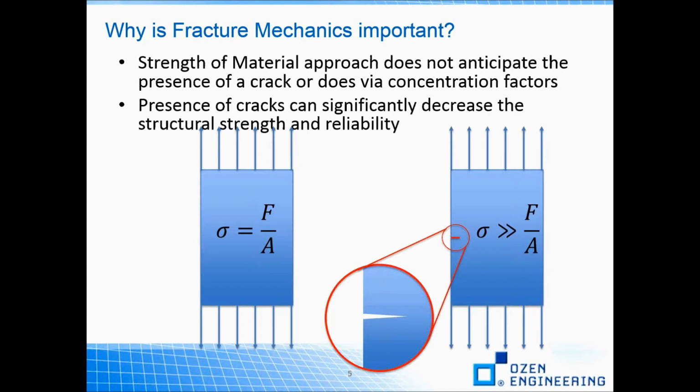It uses methods of analytical solid mechanics to calculate the driving force on a crack and those of experimental solid mechanics to characterize the material's resistance to fracture. Fracture mechanics can be seen as a special case among different philosophies. Safe life design normally uses stress life analysis, and the usual damage-tolerant design philosophy uses crack propagation, i.e. fracture mechanics, to estimate life.